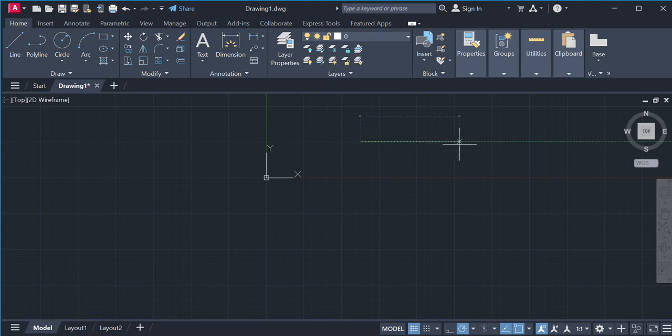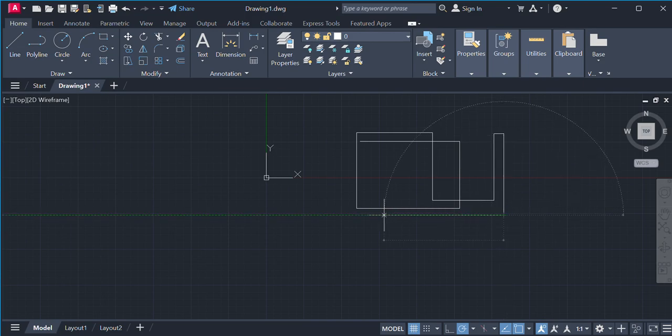This is, as it says, meant to assist you to draw lines. The hope is that you draw straight lines, but of course without the snap commands or your cursor restriction settings, it might be a bit hard. So remember that green line that shows your polar tracking, it's meant to show you that you're working in a straight line.